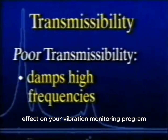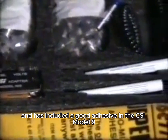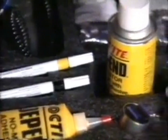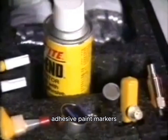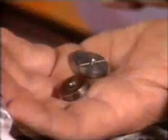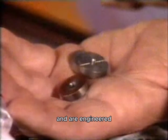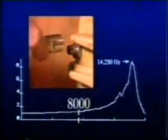CSI has done extensive research on adhesives and has included a good adhesive in the CSI Model 912 AccuTrend mounting pad kit. The kit includes 500 discs or mounting pads, adhesive, paint markers, and special accelerometers and magnets. The discs are machined of 410 stainless steel, which has magnetic qualities, and are engineered especially for use in industrial vibration monitoring programs.